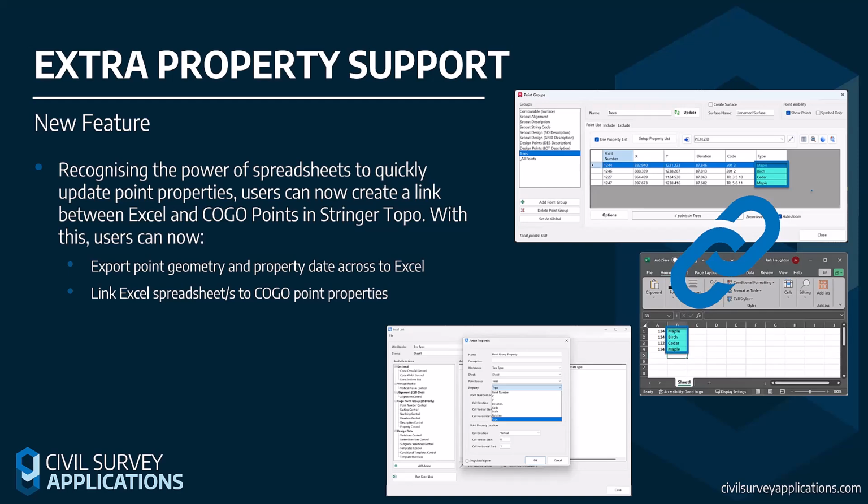So this is a great way if you have something similar to what we're going to do today, which is trees. If you're needing to add in the types of trees into your data quickly, what you can do is set up an Excel spreadsheet with those types, associate them based on point numbers. So the point number provides the software a link to the points themselves, and then update the information within the newly created type property, which we'll be creating, into the data itself.